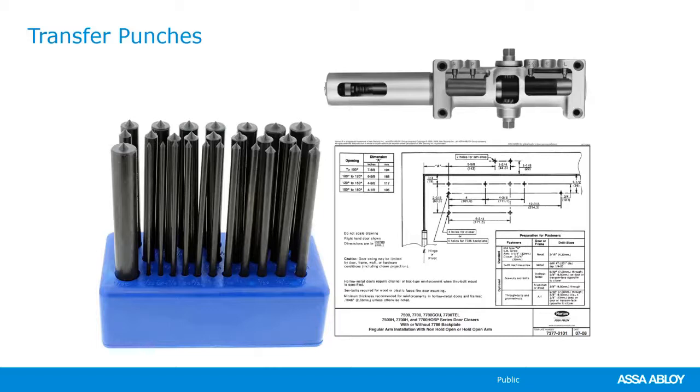And once we get that center punch drilled, we can actually line that door closer up to that mark and then use a transfer punch which fits that hole diameter of the door closer body perfectly. So we can match whatever transfer punch actually fits these mounting holes, and we can get those lined up, and it makes a perfectly centered dimple that we can then drill and get that door closer installed.